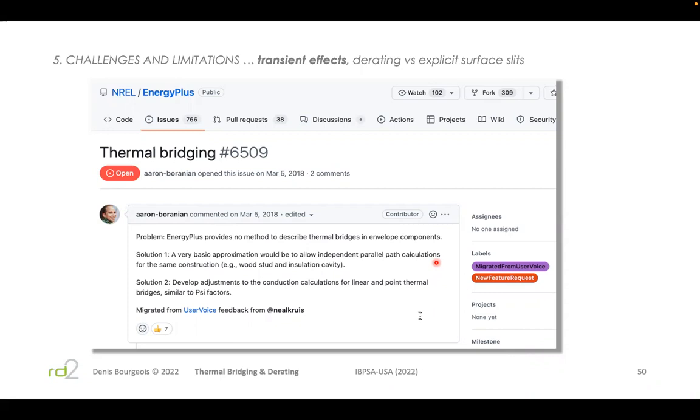If you're somewhere in the southern states, I'm talking for the North American context, if you're in Arkansas or maybe parts of Texas, maybe this is not so significant and you shouldn't be modifying the thickness of assemblies. If you're modifying insulation, I'm not so worried. There's very little thermal mass there. But if you're affecting mass timber or CLT construction, cross-laminated constructions, or rammed earth walls or adobe construction, this is not a good idea. So we actually do support you on that point.